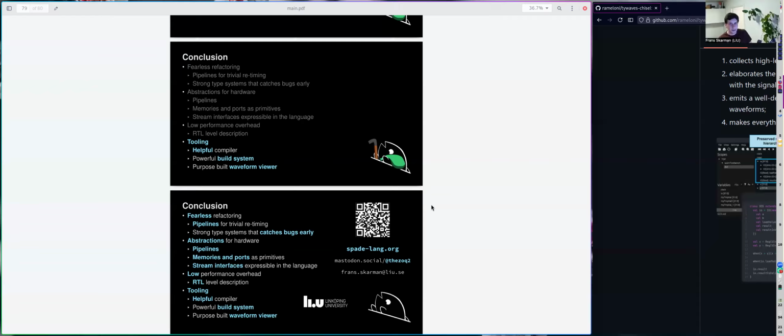Yeah, I have that challenge. I mostly work with the open source tools. I'm lucky enough to not have to deal too much with Vivado or the proprietary synthesis tools. And there you can add a source attribute to signals, and half of the time maybe that's propagated. So if you have a long critical path, you might have a Spade source line, Yosys internal stuff, Spade source line, Yosys internal stuff, and be able to infer roughly where in your code base the problem lies. That kind of works. I have had examples where it doesn't work very well.